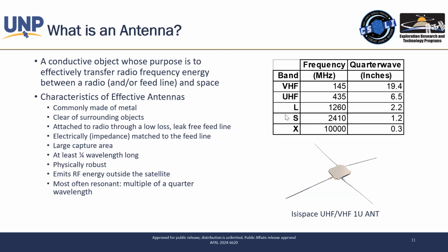The reason that we choose 1/4 of the wavelength is because in order to induce a current to resonate with a frequency, it needs to be proportional to the wavelength of that frequency. That's a really good question, actually. In fact, the longer it is, the better it'll resonate, but we need at least that 1/4 wavelength length. If you think of a dipole antenna, it's a prime example: if it's at least 1/4 of a wavelength long, then at one end it'll have the most positive peak of your signal, and at the other end it'll have a 0. That's the way that it'll resonate.